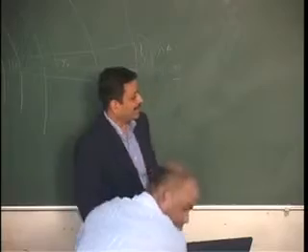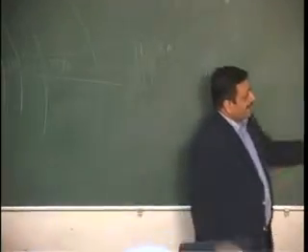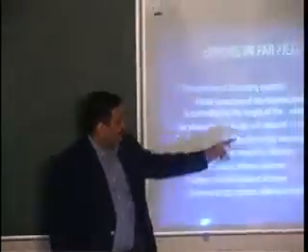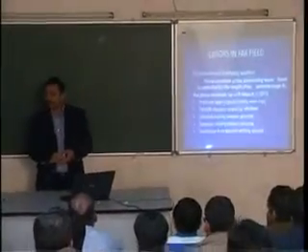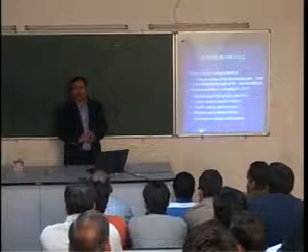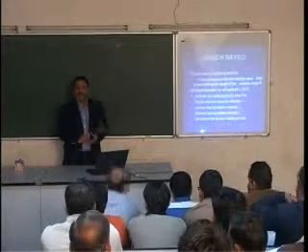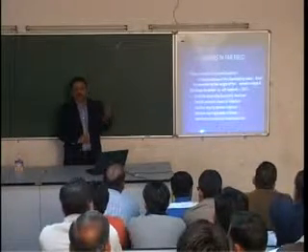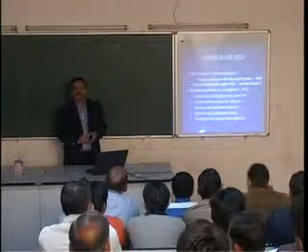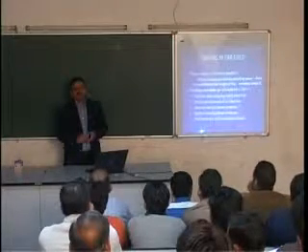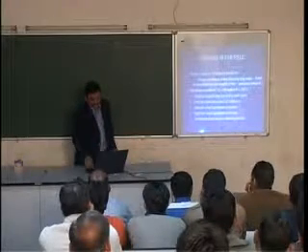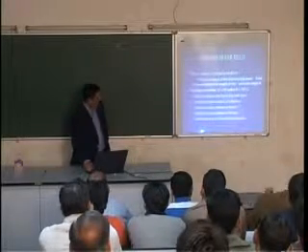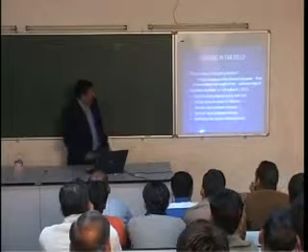So the periodic reflections. That is why we are able to get a phase variation of pi by 8, and that also does not give very accurate measurements. So you have to go sometimes 4d square by lambda or 8d square by lambda. So you may have to go to very large distances, maybe 10 kilometers or 15 kilometers, and it is not possible to do such measurements in reality very accurately. So what is the solution?